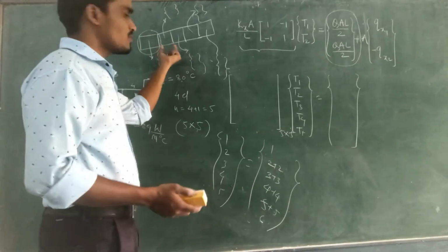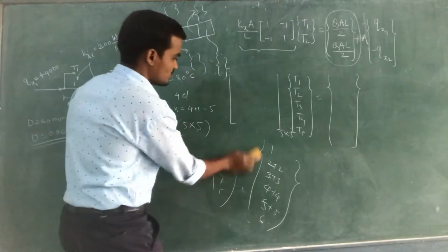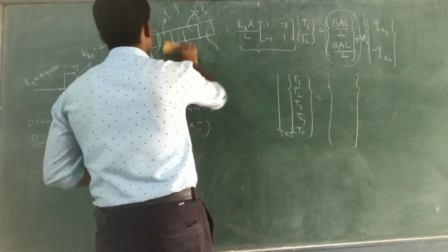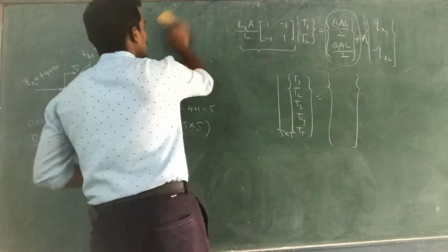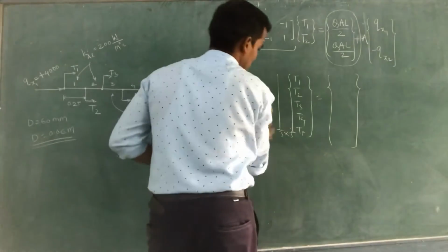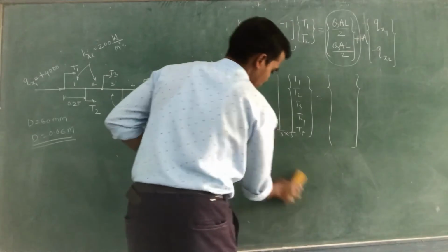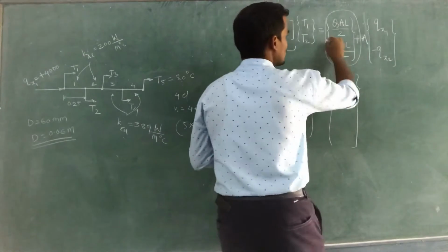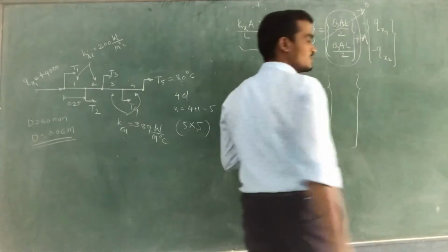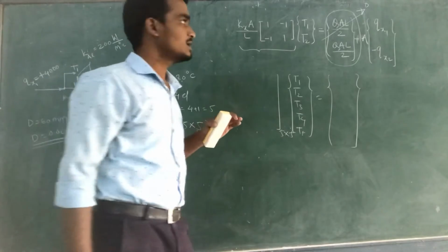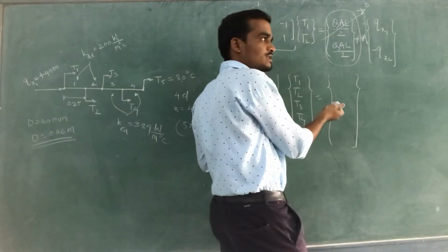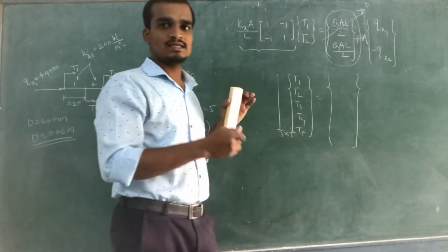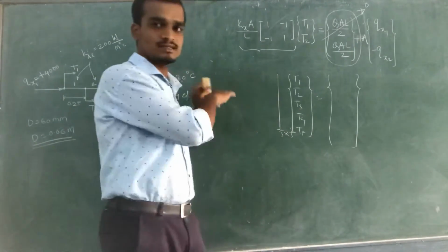So we will see such types of problems and procedures in your next lecture or next problem. Here we will just try to solve the temperature distribution due to heat flux going inside the surface of the cylinder only. Okay. So this will become equal to 0 because a heat generation source or heat generation sink is not given. Suppose if there is a heat source, then you need to take it as positive, and if there is a heat sink, then you need to take it as negative. Okay, we will explain this term in the next lecture.